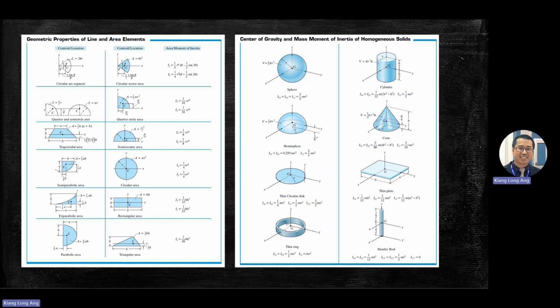So you're actually looking at the z-axis. So go and read IZZ. Here you go, I at O equals IZZ in the table, which is 1/2 m r square plus md square. There's no d there. There's no d because you are referring to O.